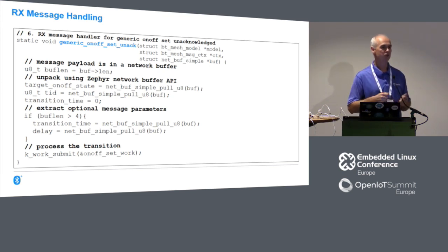Now at this point I've got the Bluetooth spec open. There are actually 3 specs for mesh. The one I've got open now is called the mesh model spec. That's where all the models are defined, all the messages are defined, all the states are defined, and I'm looking at the structure of that message. So I know how many bytes to expect minimum in the buffer. I know that's subject to some conditions, there might be more, and so on.